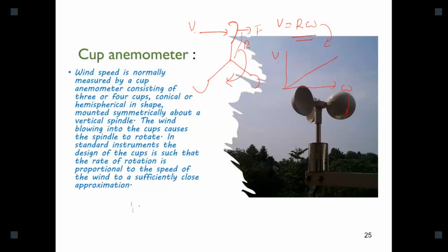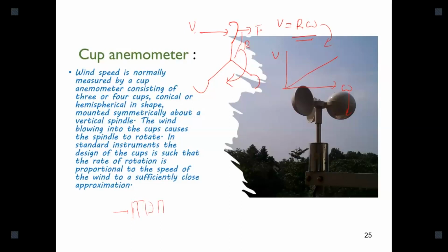Then there is a wheel, a type of slotted wheel, and light comes through it, generating a number of pulses. Then there is a counter. There is a light pulse counter because it needs to be a frictionless method to measure RPM, the rotational speed. If it were generating electricity with a magnetic device, it would apply some resisting torque. Then this is a very accurate instrument.